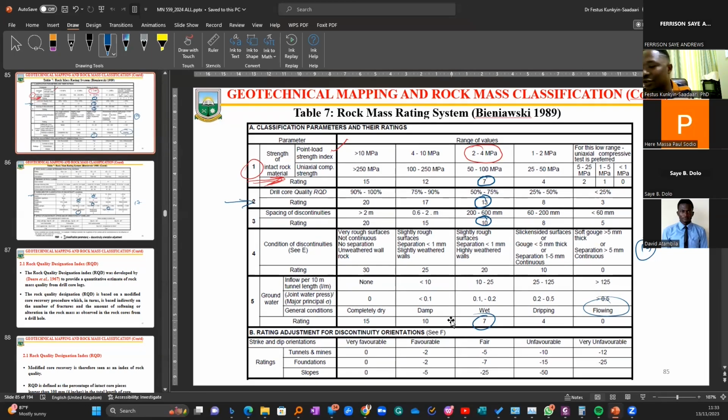All right, so now that we have gotten this, to determine the RMR value, which is not the final one, we have to sum these, the blues. 1, 2, 3. So 7 plus 13, 20, plus 10, 30, plus 17, 47, plus 7. What will it be? 54, right? Wow. So then, the next thing we do is to check whether there are any unfavorable conditions that may affect in terms of strike and dip orientation. Then we subtract them from this value we have gotten. Because if you add this, let's say you add this 15 plus 20 plus 20. So 20 plus 20, 40 plus this 55 plus this 85 plus this 100. So the entire rating is 100. The highest is 100. And we got 54.